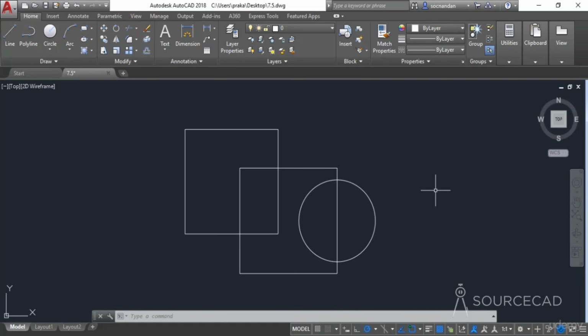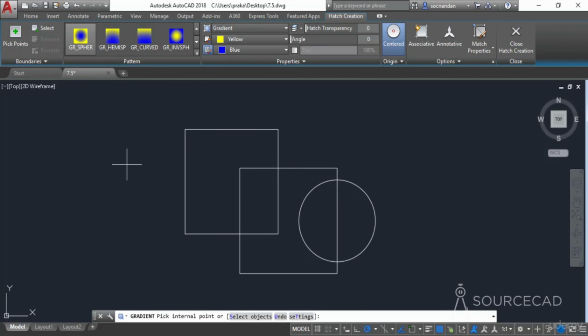In this video I will tell you about creating gradients, which are different patterns of colors in our AutoCAD drawing. So for creating the gradients, go to the draw panel, expand the flyout and select the gradient tool. Now you'll see a very familiar hatch creation tab, but we have some simple differences here. In the pattern we have these gradients, the color gradients, and also we have a new centered option here.